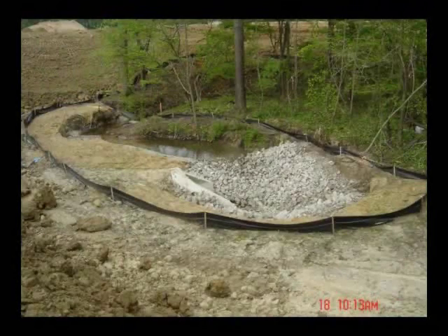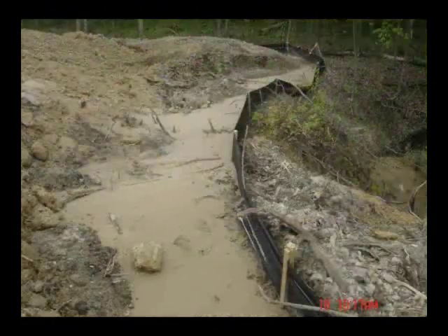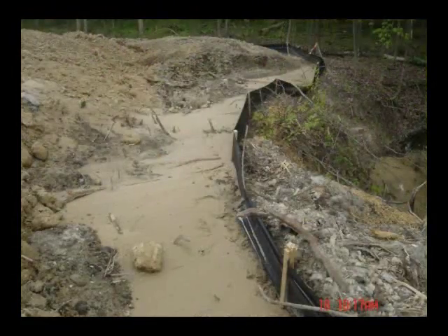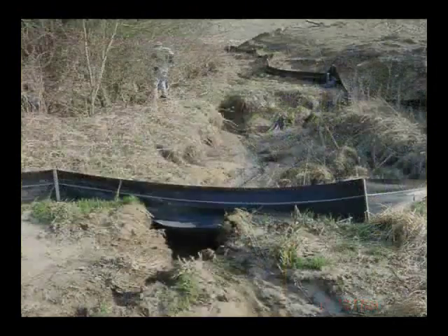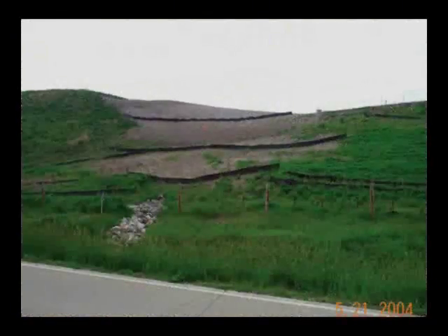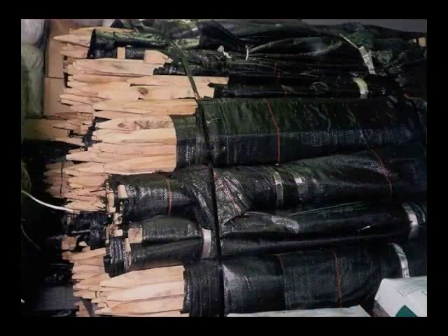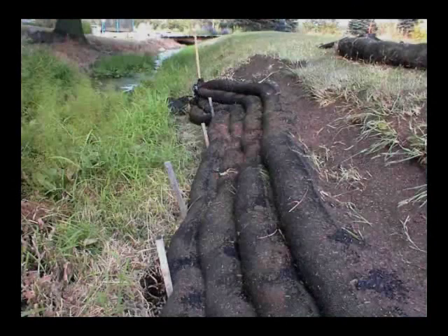Silt barriers are sediment controls intended to remove sediments in runoff by reducing velocity, causing sediments to drop out of suspension, and by acting as a filter for water passing through the barrier. Silt barriers should only be used to filter sheet flow, never for concentrated or channelized flow. Silt barriers must be placed along a horizontal contour perpendicular to the direction of sheet flow. Several types of silt barriers exist. The most common are silt fence, straw wattles, and compost socks.